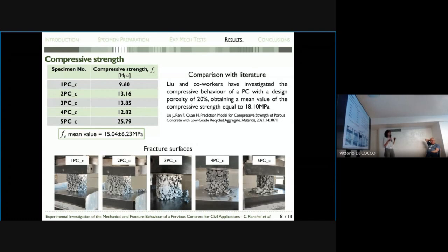As a matter of fact, under compressive loading, all the points on the same plane of the PC are stressed at the same time, and the cement paste usually breaks first due to the small bonding interface. Then, when the cement paste breaks, a part of the stress is transferred to the lower plane, whereas another part is absorbed by the aggregate, leading to the failure.